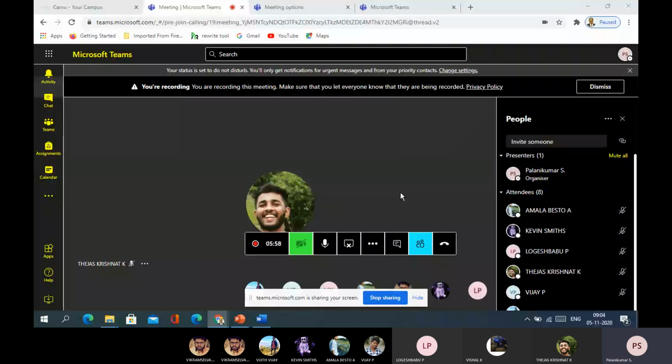For example, any railway system can be divided into three different categories: one is the main line, another is the suburban, and another is the city line. In the city line, I think you may know what infrastructure is needed. If we go for electric traction, a single catenary wire is enough, whereas a double catenary or some complex catenary arrangement is needed for the main line, because the catenary is deciding how much speed the particular train is going to reach.